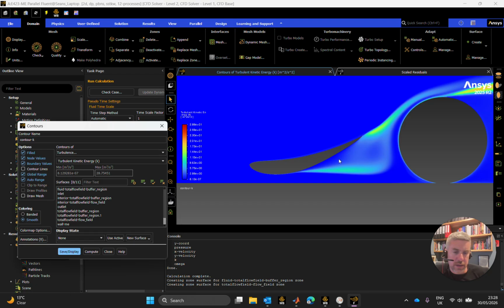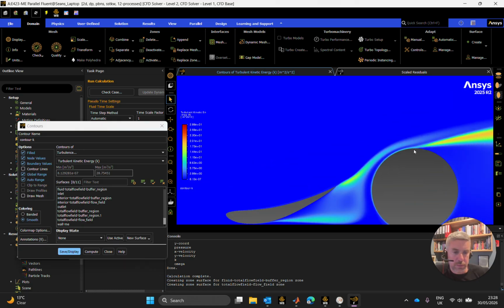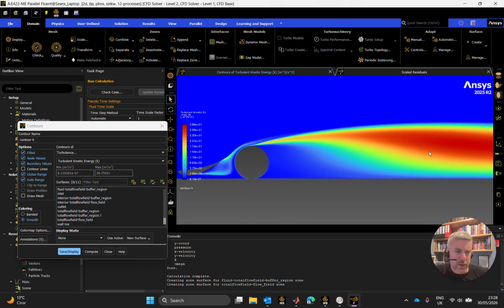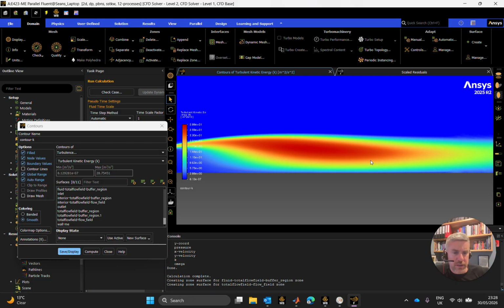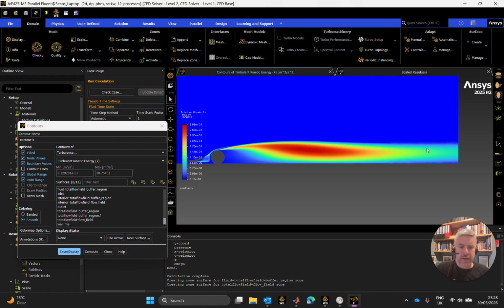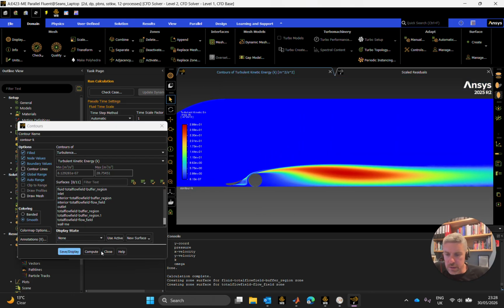So this is that zero velocity kind of tumbling region, if you like. We're picking up a wee bit of turbulence, obviously coming over the top of the wheel. But we see the wheel maybe drawn in a wee bit here, and again that sort of a wake pattern coming off the back of high turbulent kinetic energy in this region here before it drifts off again. But we definitely have a lot of what you might want to call dirty air coming off the back of it here.